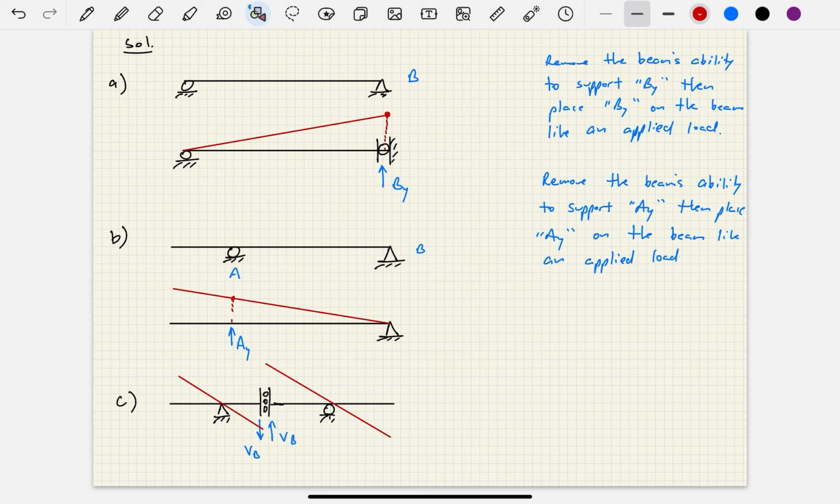And then I've got this discontinuity that shows up right there at the cut. And so look at that. This right here is a piecewise segment, two parallel segments generating that influence line for shear. And again, we've seen that before in a previous video example where we saw the influence line for shear creates two parallel lines. Okay, now that's shear.